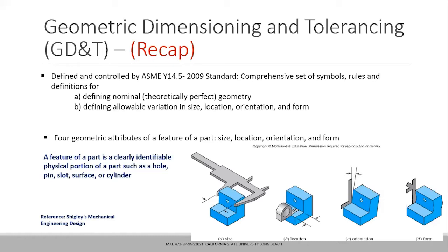So if you would like to have a perfect form, perfect perpendicularity, perfect orientation, and very tight tolerances, what will happen? It would put an enormous amount of restraint on the manufacturer to fabricate it, and second, it is also very difficult to inspect. With very tight tolerances, it will take a large amount of time to inspect them for quality control. It will require very precise machining and fabrication processes. So it will unnecessarily increase the cost of manufacturing.